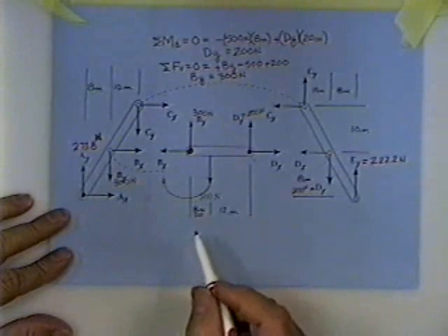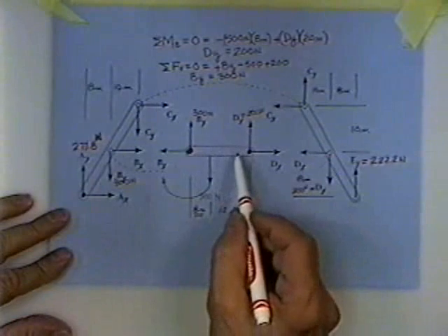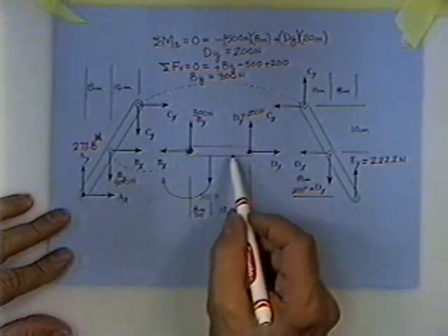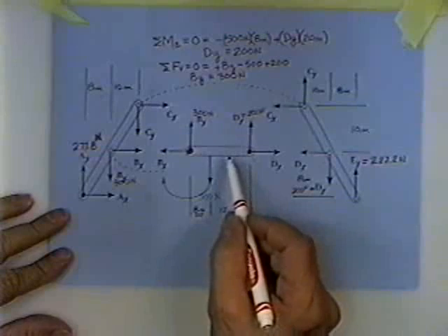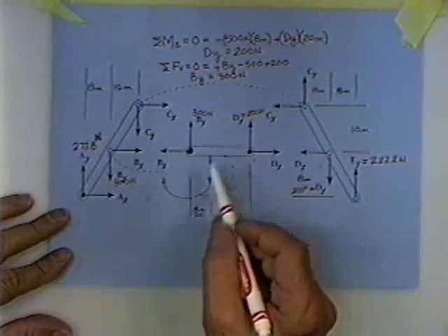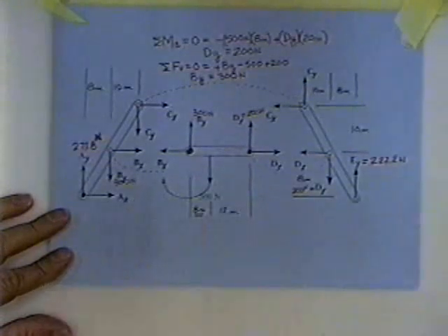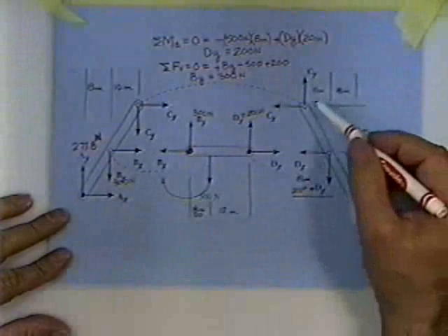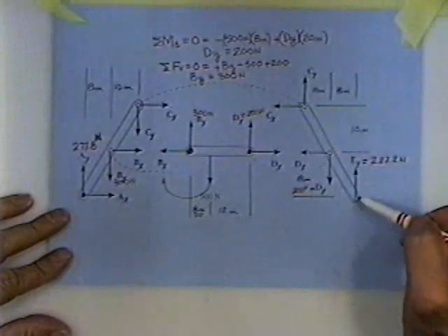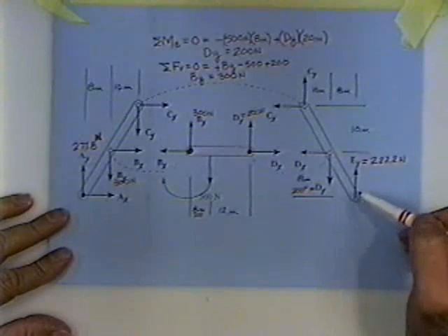Alright, now there's nothing else I can do with this free body, member BD. Anytime you run out of things to do, even if you're not sure you see what else to do, don't worry about it. Just skip over to a different free body and use it to pick up some answers. For example, member CDE. Member CDE has 3 unknowns acting and 2 things I've already found.